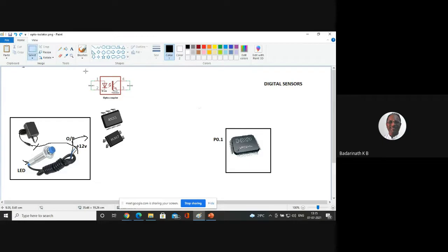So now we will see how the opto-isolator works. These opto-isolators are also called optocouplers. We have two components. At pin number 1 and 2, a diode is there. It's not a normal diode, it's an IR LED or photodiode. We can call it a photo LED. The other side, the other two pins, is called a photo transistor. You can call this the A side, and this the B side. You can see that the A side is not connected to the B side.